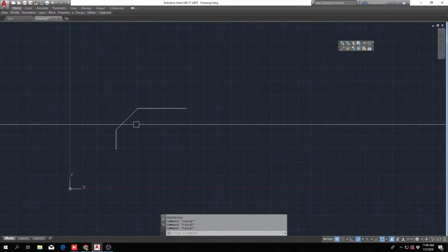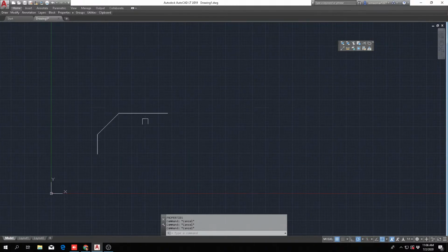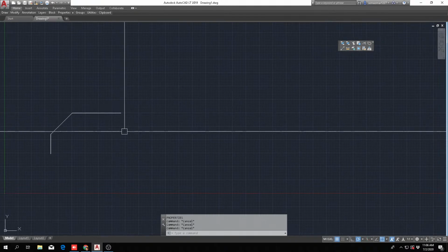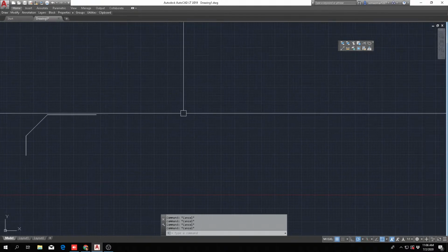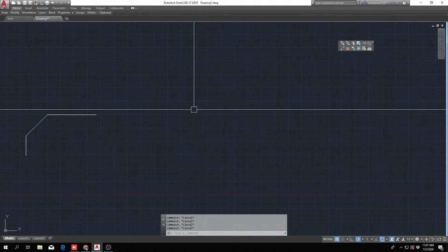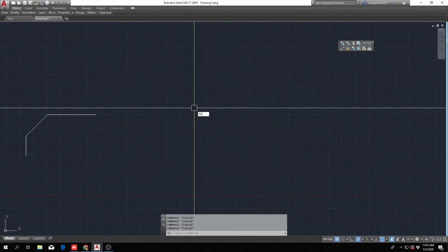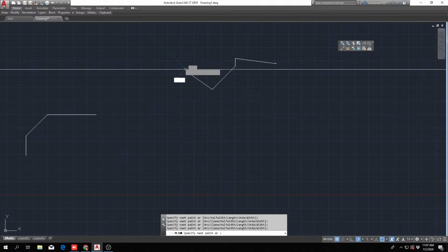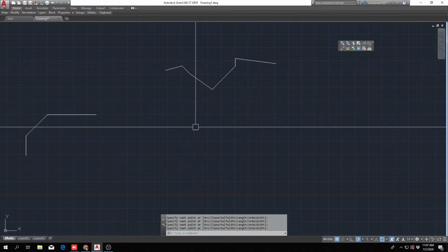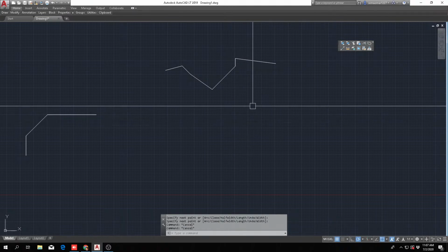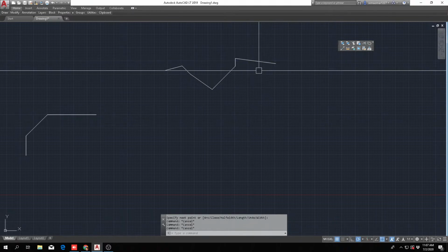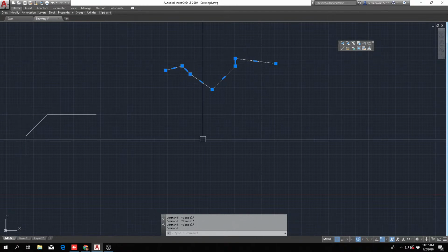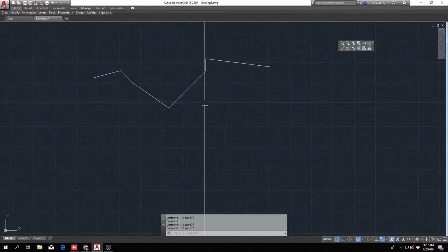That's the chamfer command. Now let's do a P line. Remember how to do a P line? Very easy. PL, enter, and just draw whatever. It doesn't matter what it is. Just draw some lines, then press escape. Just remember, a P line is lines that are attached together.